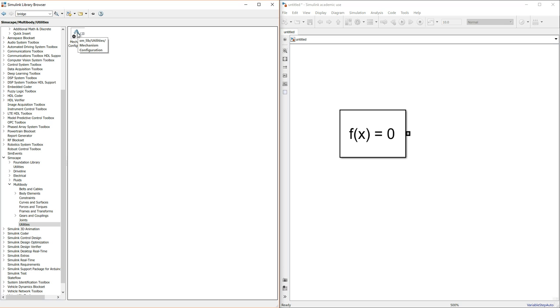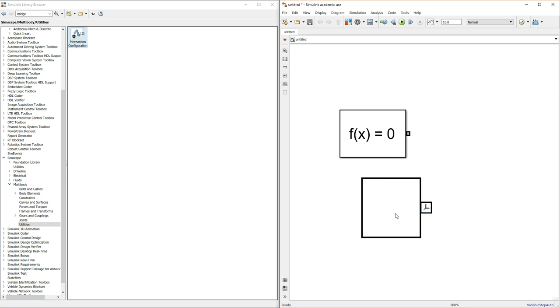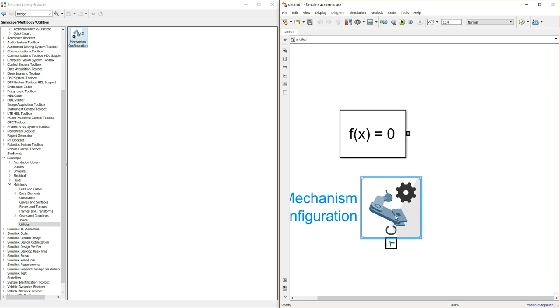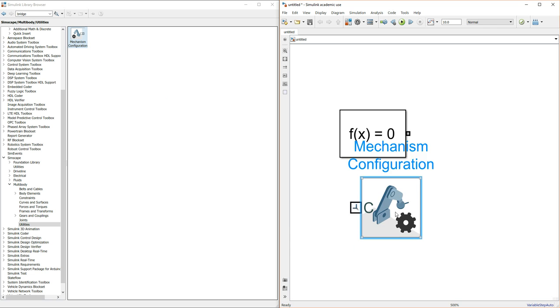Don't forget, in any types of these simulations, everything is defaulted to Z. Z will act purely as our gravitational aspect. It does not shift in Y. All rotations, all prismatic behaviors, all appear in Z. So keep that in mind, because it will help you as you're going through. So let's drag that in. It's going to flip that up. Remember, Control and R.